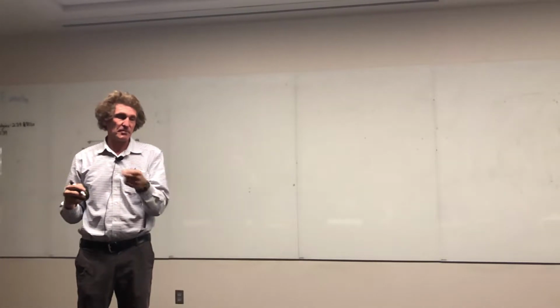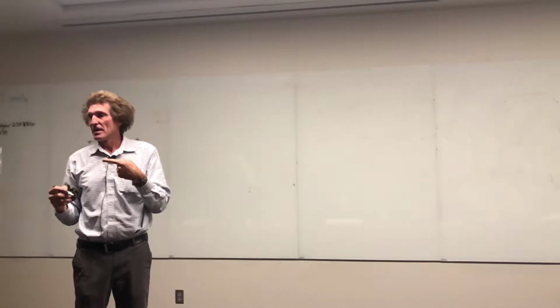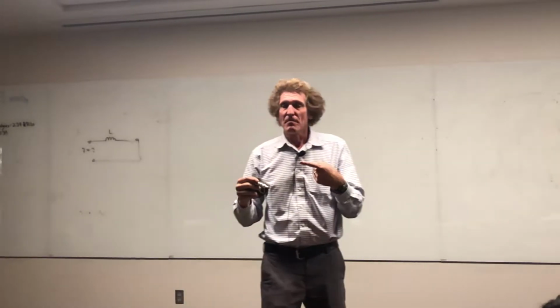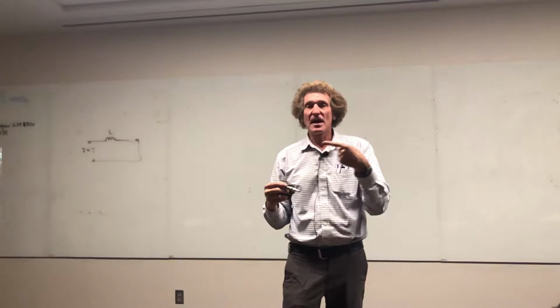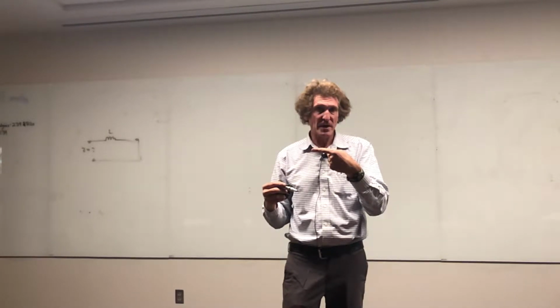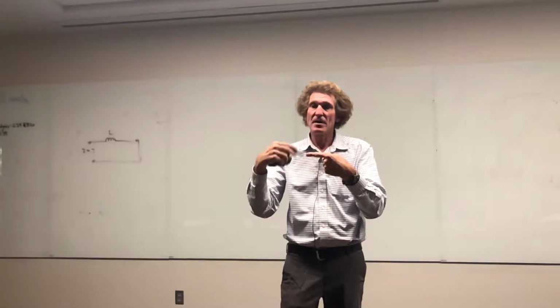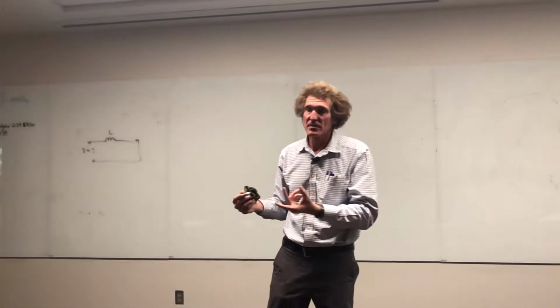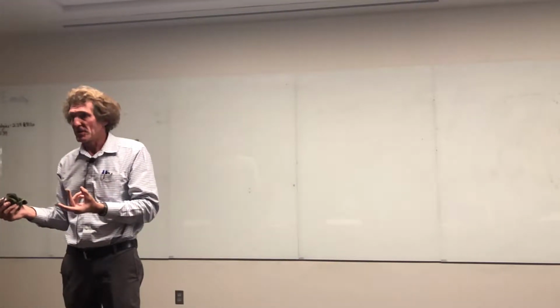Did you have to make inductors and measure them or not? You did? I haven't done it in EMC in a while. But normally, what you do is they take something that's got an iron core of a certain radius, and then they start wrapping shellacked wire on, maybe 100 windings. And then you apply a certain voltage at a given frequency, maybe 1,000 hertz, and you measure the current drawn by that. Then you can figure the impedance.